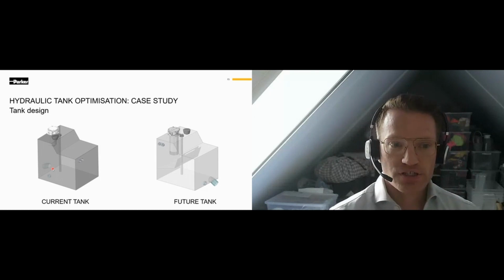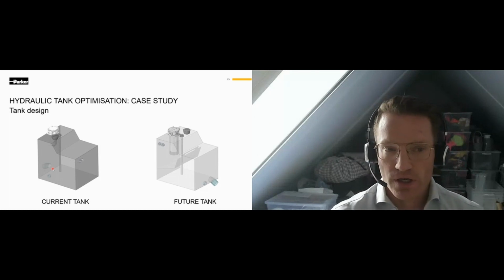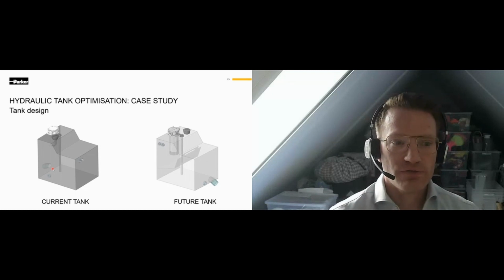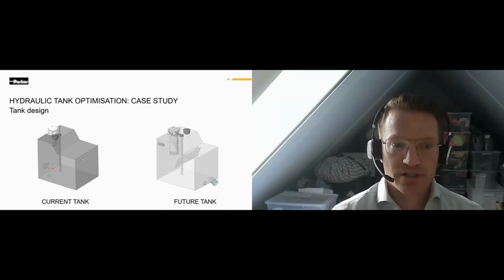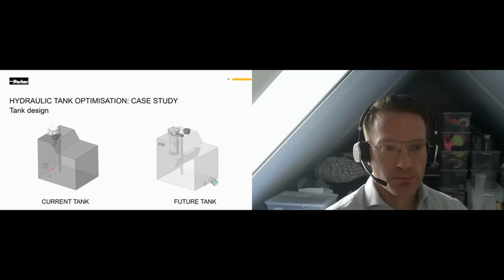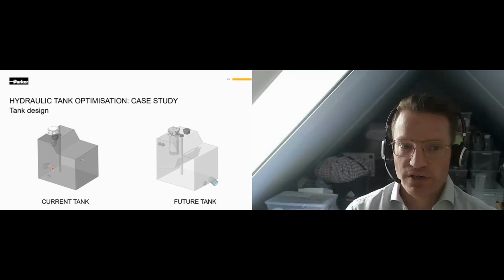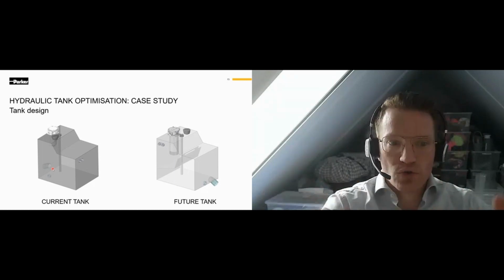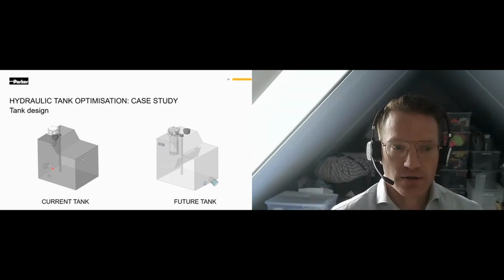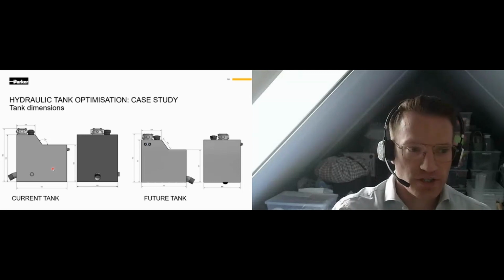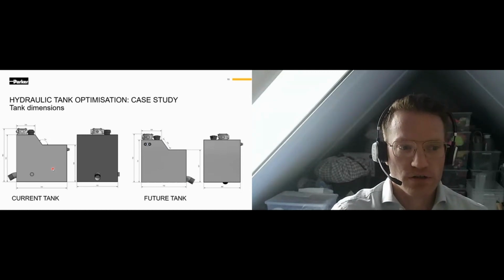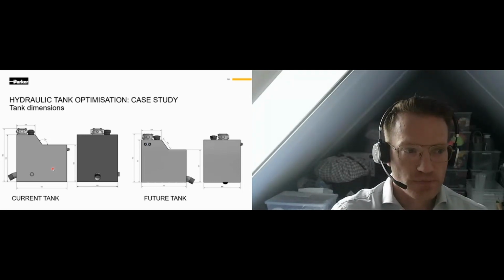And the second important thing is to reduce the flow velocity. And with our GLF filter, we can reduce the flow velocity, and we can even control, let's say, the release of the oil into the tank. In this particular situation, we've chosen a perforated funnel over 270 degrees for a horizontal release of the fluid inside the tank to give us the optimized results. This is difficult to see, but the tank has been reduced roughly by 20% from all directions.